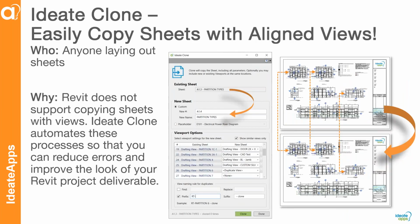And then Revit does not allow you to duplicate a sheet. There's just no tool allowing you to copy a sheet. But we're allowing you to copy a sheet with our Ideate Clone, but also giving you access to the viewports on that sheet. And you can decide if you want to duplicate, or duplicate with detailing, or swap one viewport to another. So I'll show that in just a second.